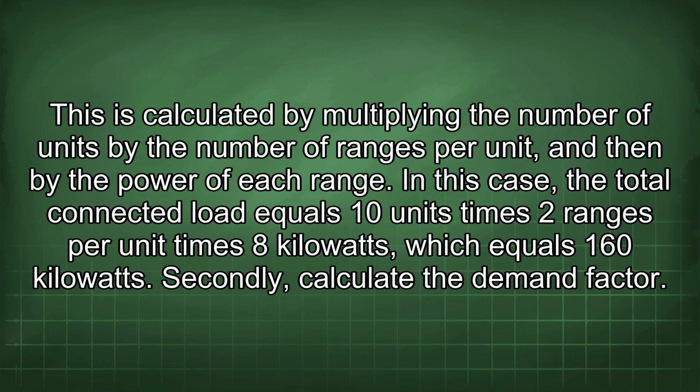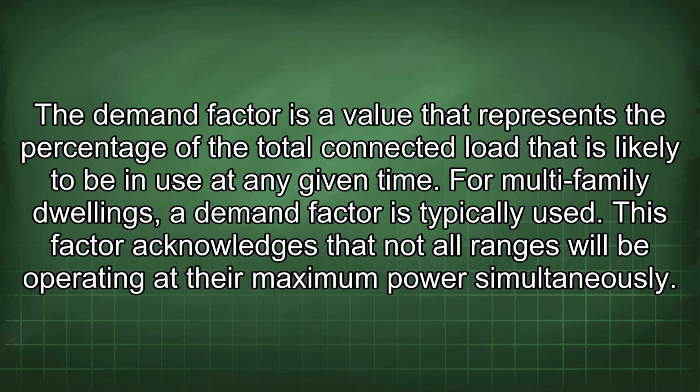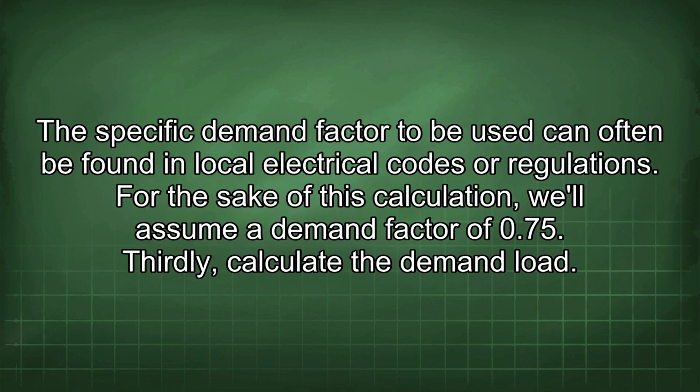Secondly, calculate the demand factor. The demand factor is a value that represents the percentage of the total connected load that is likely to be in use at any given time. For multi-family dwellings, a demand factor is typically used. This factor acknowledges that not all ranges will be operating at their maximum power simultaneously. The specific demand factor to be used can often be found in local electrical codes or regulations. For the sake of this calculation, we'll assume a demand factor of 0.75.